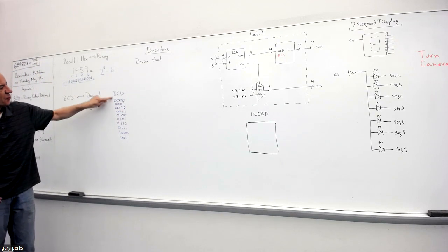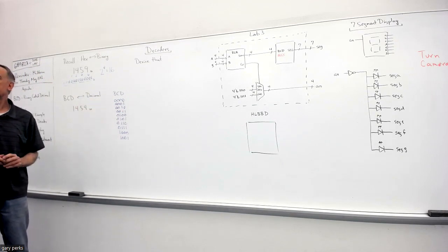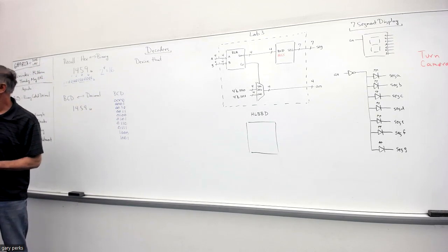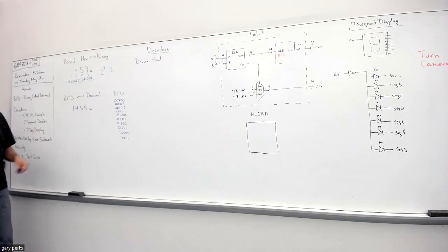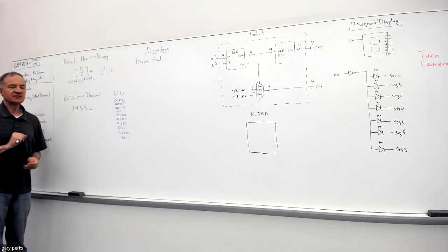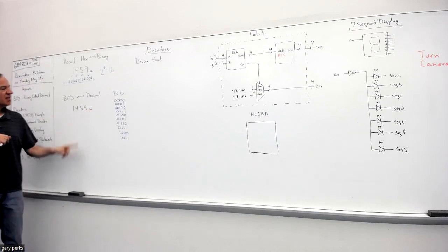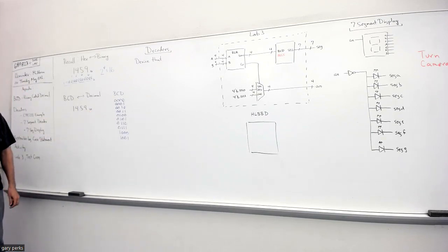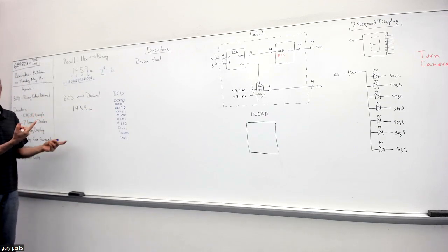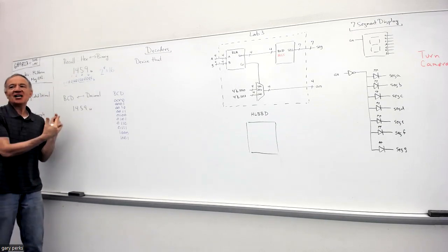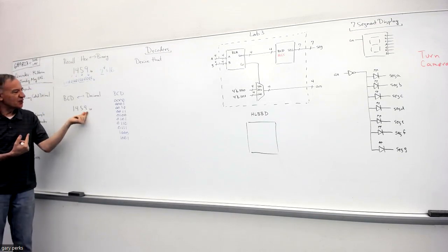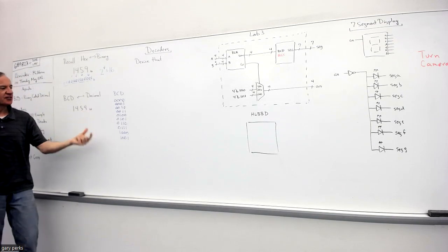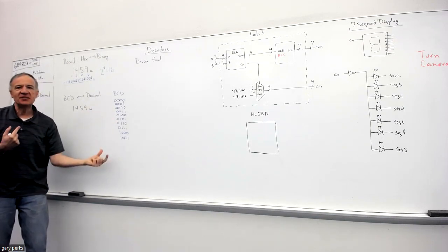See, BCD has the 4-bit binary for all your decimal numbers, characters 0 through 9. Okay? So if I have a base 10 number, like 1459, and I want to show that base 10 number in BCD, I'm doing the same sort of thing as we do when we go from hex to binary, but the key difference is I'm not doing a conversion here. This is not converting bases, okay? This is just representing each decimal character as a 4-bit binary group that we call BCD.